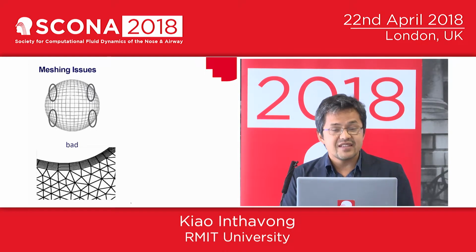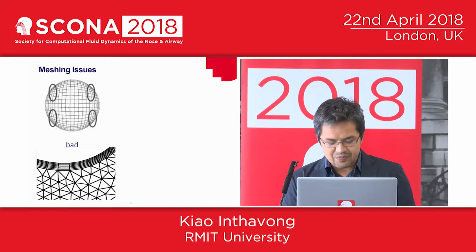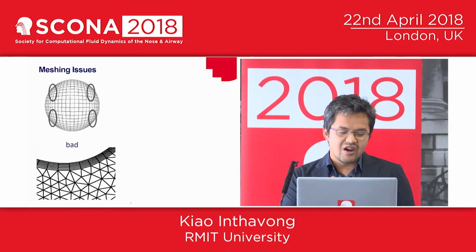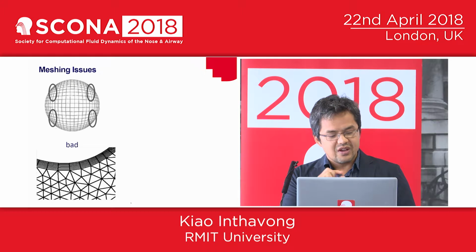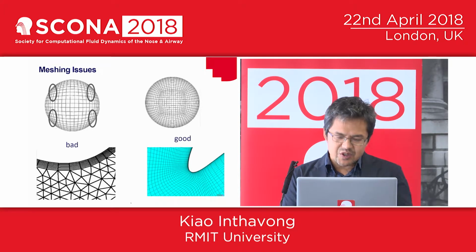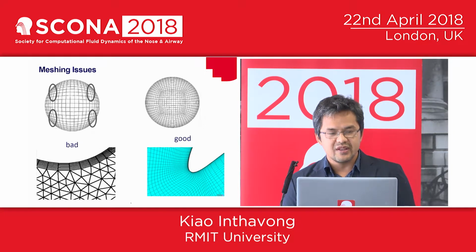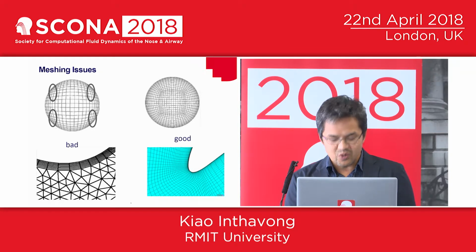So just an example of the meshing issues we have. So these two are quite bad because you have high aspect ratios and skewness in the corners of that circle. So a high skewness for the circular geometry, and the one below it is bad because it has high change from a very narrow to a large mesh at the interface between the prism and the tetrahedrals. And so you have strategies to change that, and so I think this is the kind of reporting that we would want to work towards when we publish our results, to ensure that the quality is there.